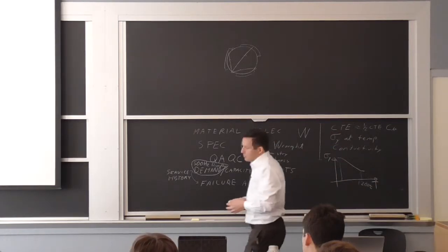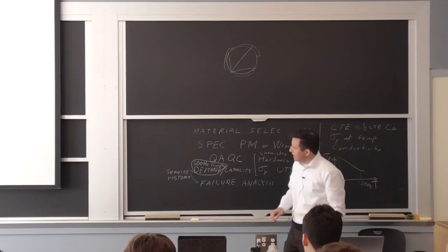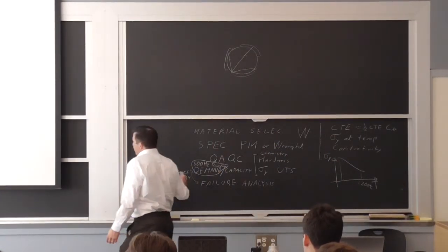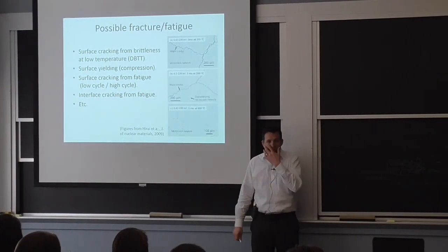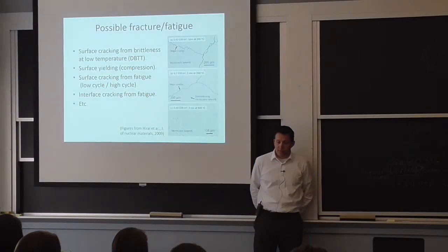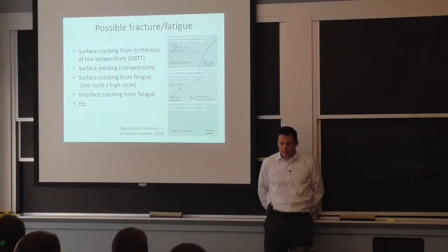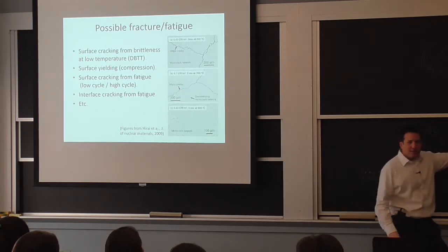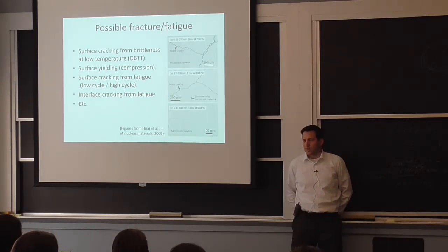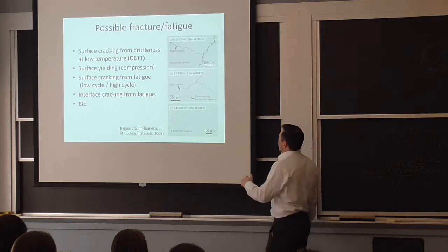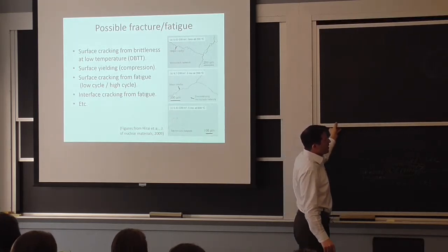I don't want to go through necessarily all the details of the cracking, but I'll say something about the failure analysis here, which is they were getting grain growth. And we'll talk a little bit about that. And they were really worried about, well, okay, what am I going to do here? Maybe the alloy isn't right, there's something going on. It shouldn't grow under the beam current and those temperatures, but it does. So what we concluded was the grain growth was really something that happened after you had a few cracks that were going in plane of the target.